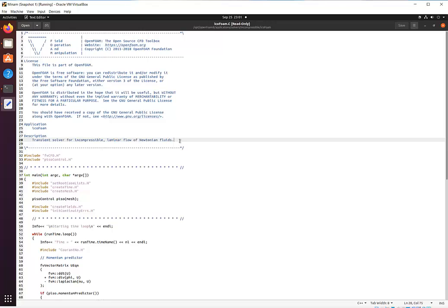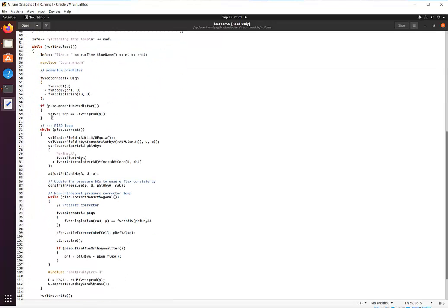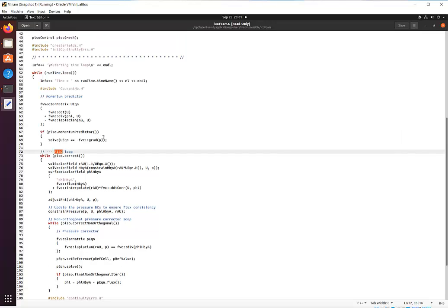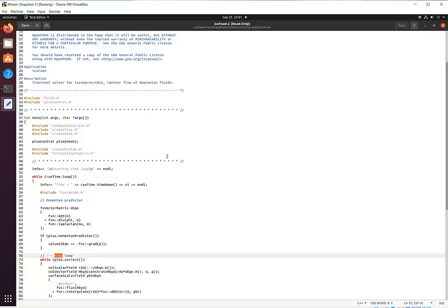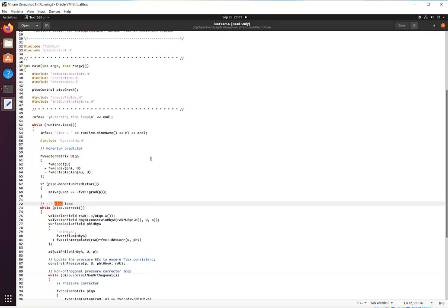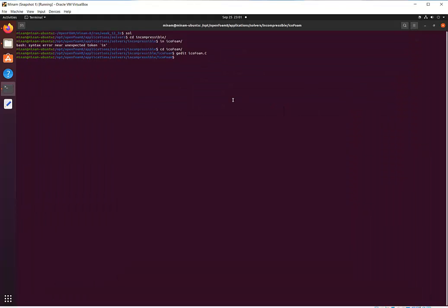So the fluid that we have considered is water, which is of course Newtonian in nature, and the flow is laminar because the Reynolds number is 2100 and it's an incompressible flow. We see that this algorithm applies a PISO algorithm, which you could find in any literature. And of course, in order to understand the complete algorithm in C++, we will have to understand the language, which at this point of time I'm afraid I don't know much about.